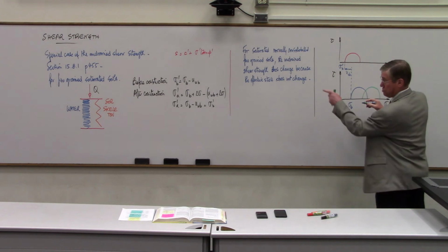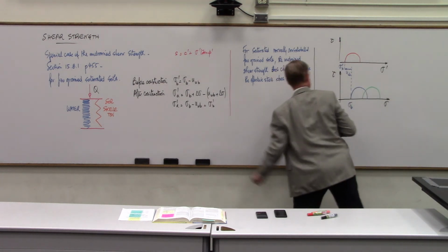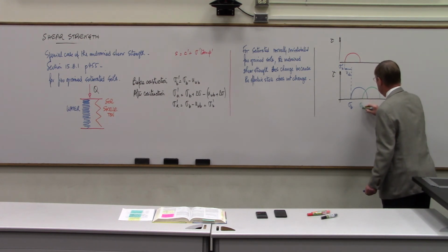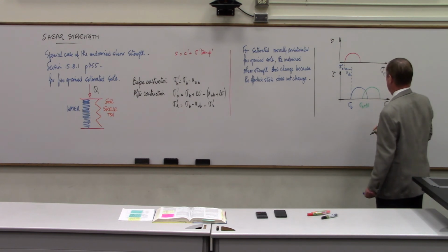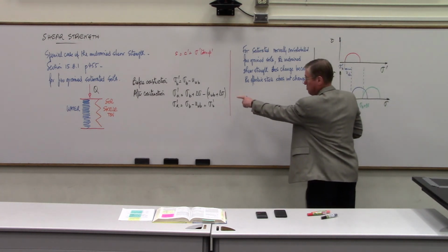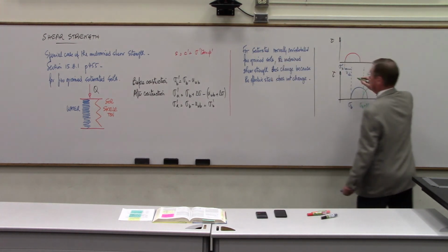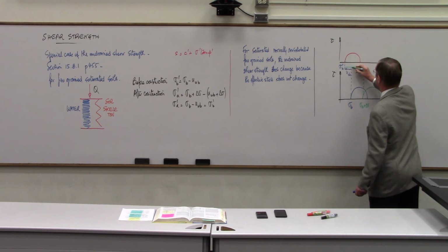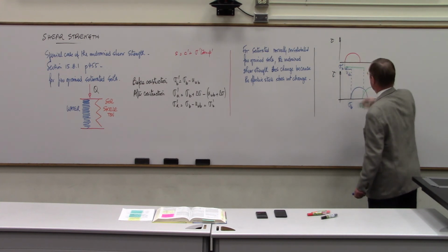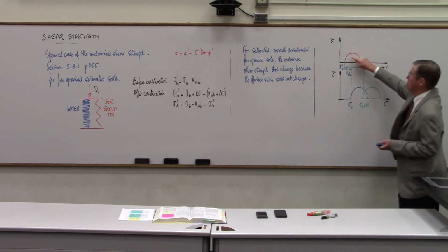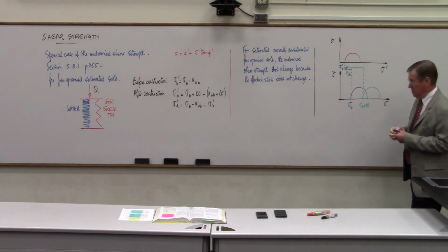And then I increase to sigma B plus delta sigma. So the green one here is associated with sigma B plus delta sigma. But the water pressure has increased by delta sigma as well. And it's equal to u_wB plus delta sigma. So I actually go back to the same value. In other words, even though I've got a different circle on the total stress set of axes, I've got the same circle in the effective stress set of axes.